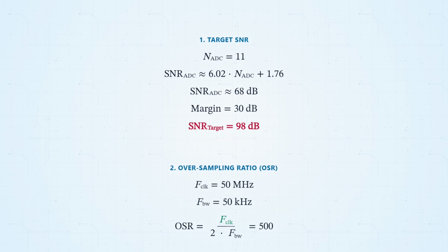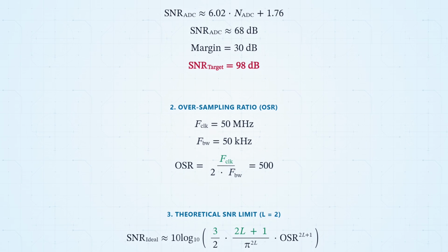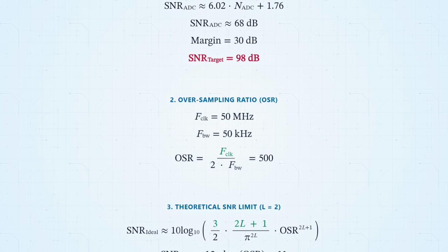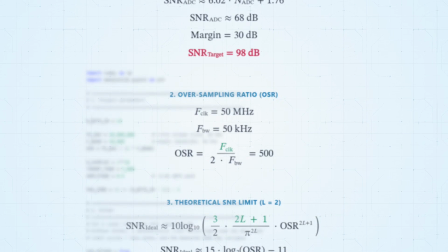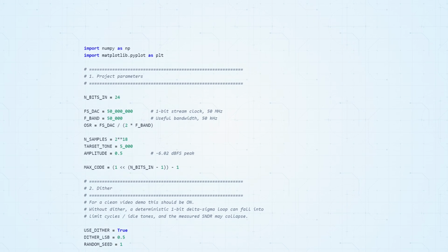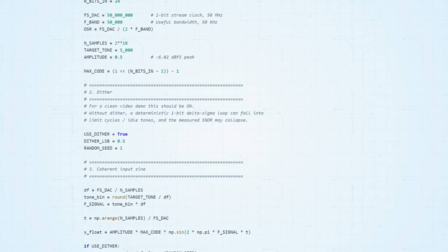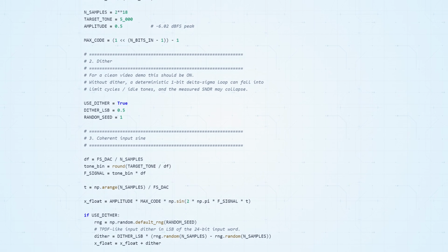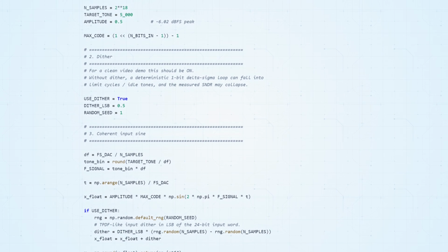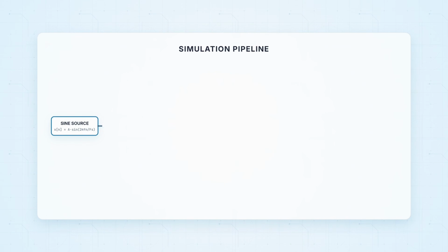Theoretical calculations alone are only half the job. Real engineering starts with thorough verification. To validate our mathematical estimates, we have constructed a complete software model of the delta sigma modulator. Let us define the baseline parameters. The input data stream will have a resolution of 24 bits, and, for our test signal, we will generate a mathematically ideal sine wave. Yes, a pure sine wave creates somewhat idealized test conditions. However, at this specific stage of development, it is exactly what we need to clearly visualize the fundamental mechanics of the algorithm in action. For those who want to dig deeper, here are the implementation details.